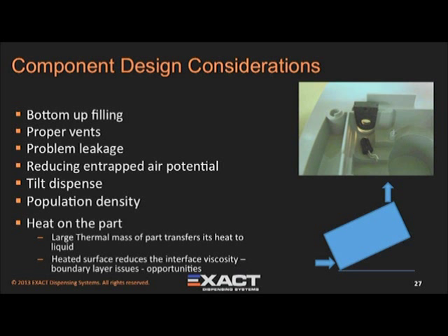The design of your components can also help a lot to prevent potting problems. We encourage you to evaluate bottom-up filling options that allow resin to enter the part from the bottom and exhaust air out the top. We have pictured not only bottom feed, but a tilt dispense approach that eases the evacuation of air from the part. These kinds of design should be considered. We also, periodically, have found that by dispensing resins onto a heated part, boundary issues between the resin and your part are influenced, allowing better fill results.